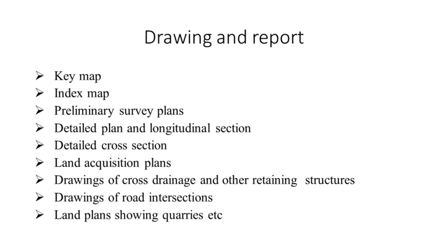Okay, so now the reconnaissance survey is over, ground reconnaissance survey is over. In that we are going to collect the topographical data. Second stage is the preliminary survey. In that case, we are going to fix the road traverse, and we are going to take the measurement of angle and distance. Okay, after that the next survey, what is it? Nothing but the final determination of the final central line in the design office. So after that we are going to finalize the central line in the design office. Up to that, next is final location survey.